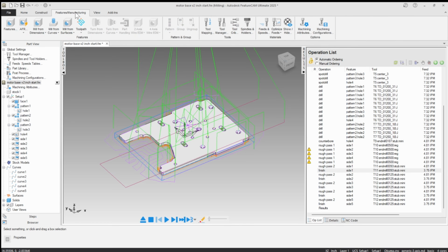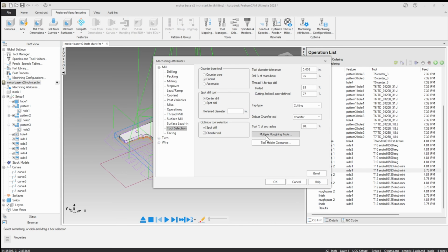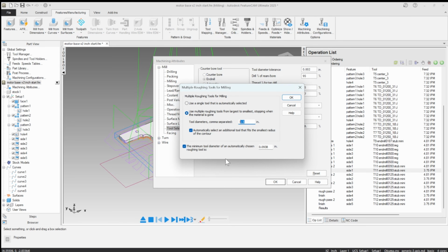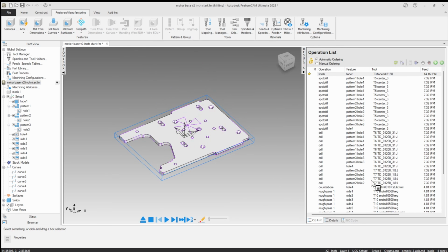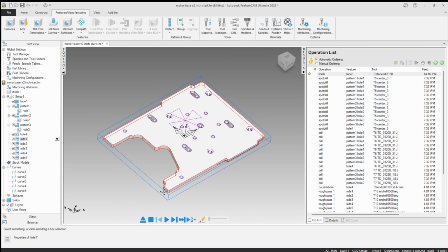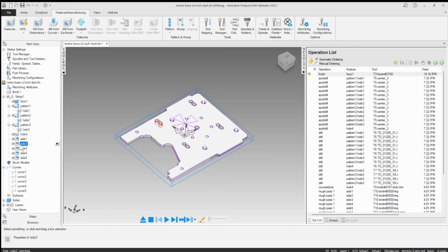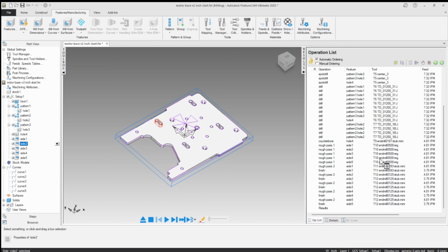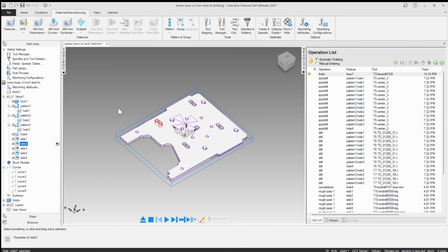If you remember from the machining attributes, I said, hey, let's use a 1/2-inch. So it tried to, but in that case, that particular feature, whatever that is, so we've got side 1, which is cutting around the whole perimeter. We're okay on some of these, right? And then on side 2 and elsewhere, we were getting that warning saying, hey, the tool's too big.